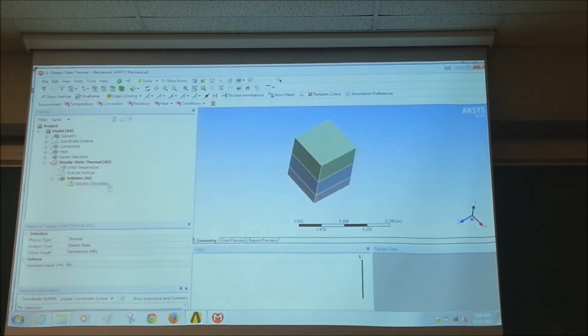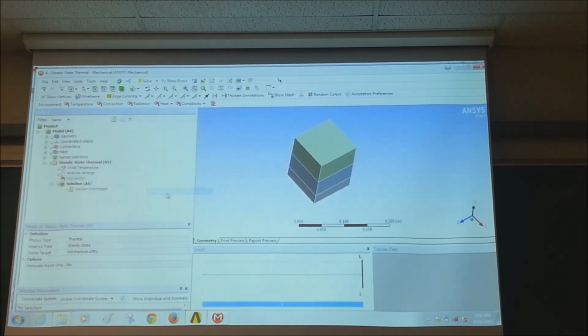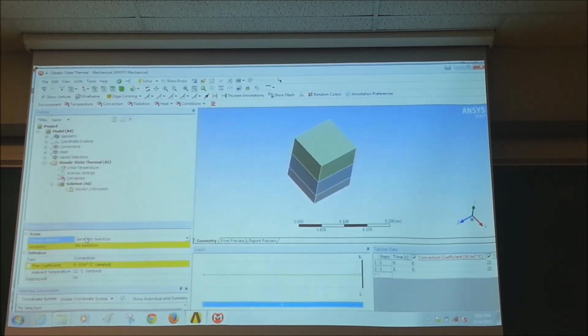And very simple problem, right? So now you got to know physics, right? Physics says the boundary value. Everything is going to be adiabatic except the top and bottom. So let's just insert a convection boundary condition at the top. So geometry selection, I've done my dirty job. I've taken time to create it. I don't need to pick a surface, because you notice this is fairly simple, so it picks the top surface. H coefficient, right? And the film coefficient, let us say